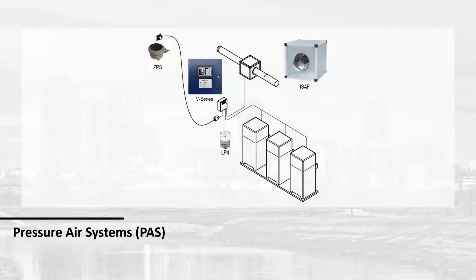Do we have products that combine intake and exhaust in the same pipe? So we do not deal with vent piping. I don't know if Austin and his team do. Typically, concentric flues are appliance specific. If you're not approved for a concentric vent by the manufacturer, you can't just do that as a field thing.